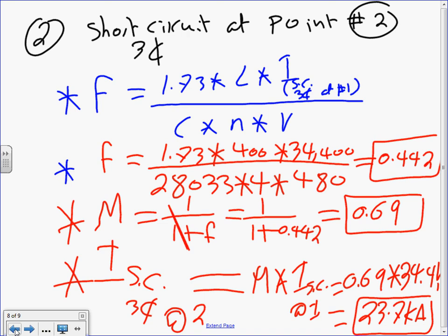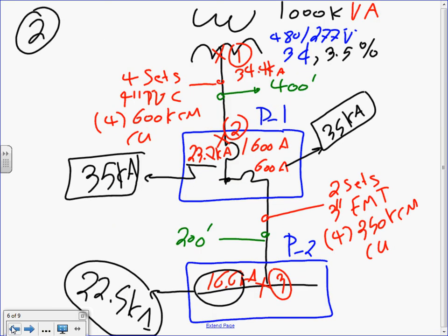The second thing I wanted to talk about, guys, is sometimes the impedance, you see that 3.5. Zach, if you look at the book that we have, they multiplied the 3.5 by 0.9 because the impedance is plus or minus 10%. They don't know exactly the exact impedance value of the transformer, so they give you a value within plus or minus 10%. Some engineers cut this value by 0.9 to use the worst scenario, which is the smallest impedance, in the calculation.